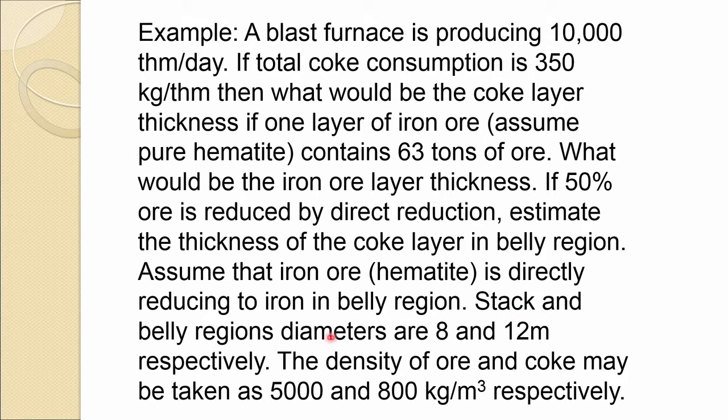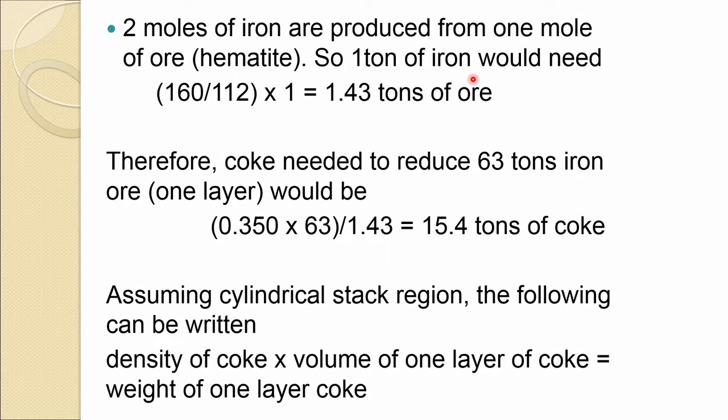Stack and valley region diameters are 8 and 12 meters respectively. The densities of ore and coke may be taken as 5000 and 800 kg per meter cube respectively. So, here you have to find out the coke layer thickness and your ore layer thickness in the valley region and even the stack region. So, how would you do it? Now,